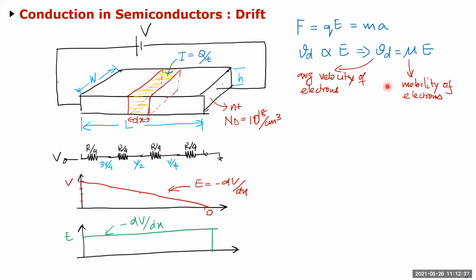Even so, for example in analog design, I don't do designs in 14 nanometer and all that. They're usually 90 and 130 nanometers, but we still use long channel equations for hand calculation, and then you just do simulation. In analog, most of the time you're using long channels anyway, so your equations are valid. It's only in digital that they use the shortest channel possible. But in that case, you don't have to be super accurate. You can be accurate to 80-90% and then use the simulator to verify your design.